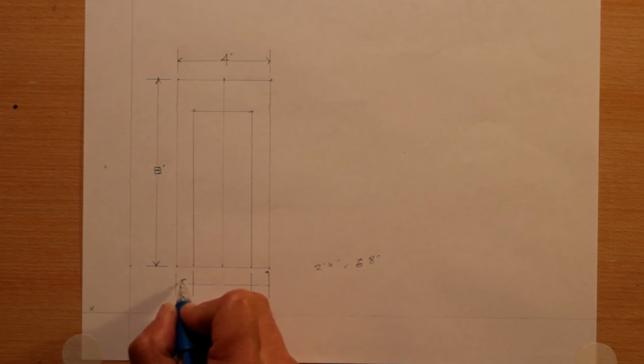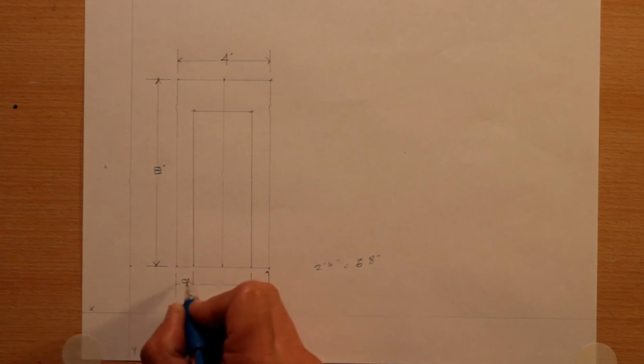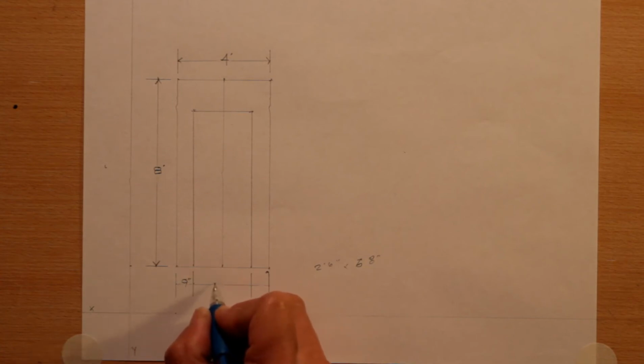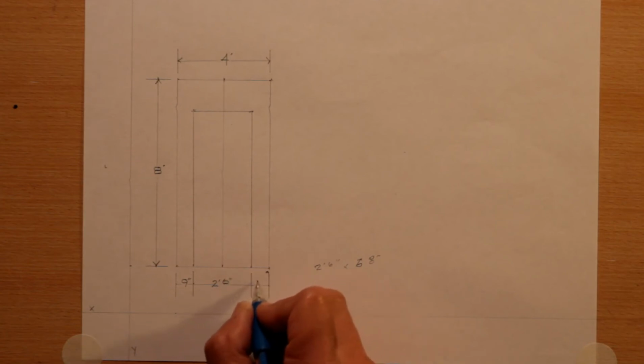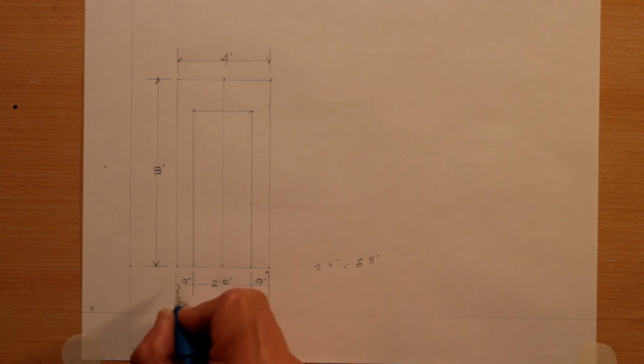So, on the right-hand side of your flat, you will draw the extension dimension lines for your doorway height. All the same techniques apply. You are simply drawing them outside of the flat to avoid confusion with anything drawn on the inside.